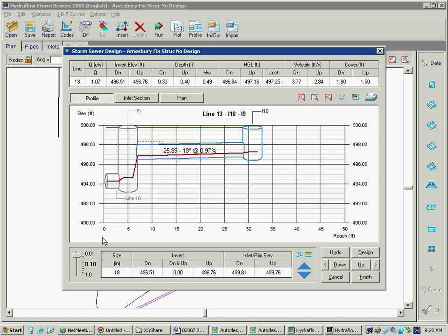That's about 1%. It's sort of an odd interface, but the way it works is these arrows over here for moving your pipe invert up and down move in increments selected over here. So if I want finer increments, this will move it in hundredths of a foot. So you can see it's moving much slower now, or if you need to move a large amount, you can move in up to 1 foot increments. So it's pretty simple to use.